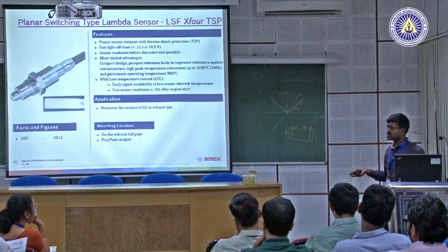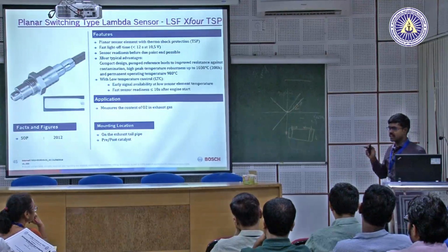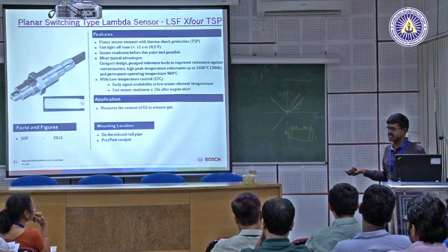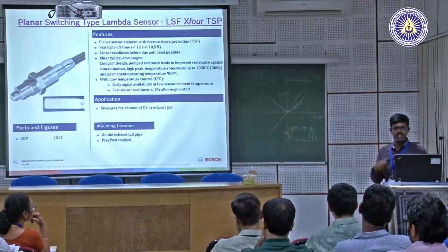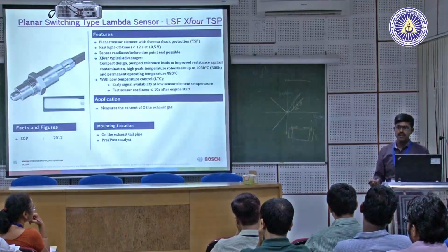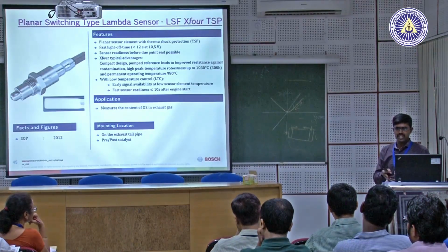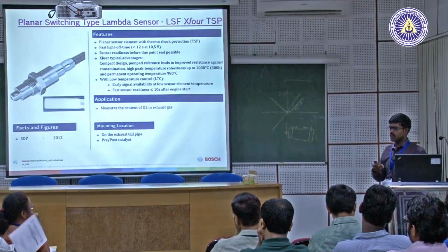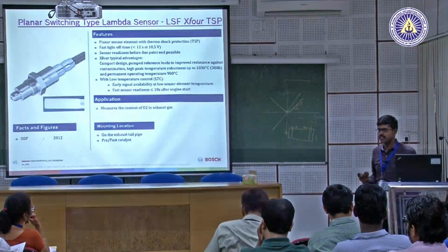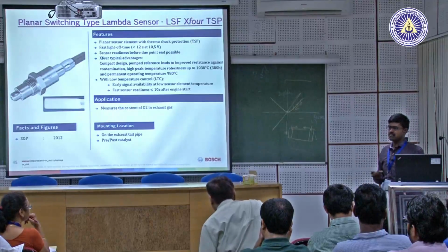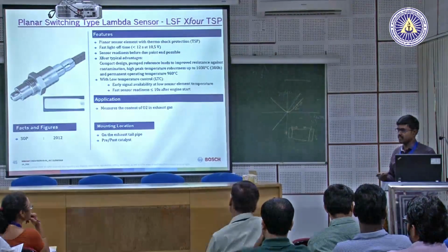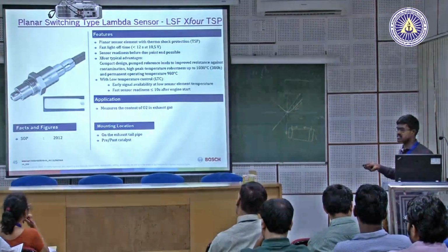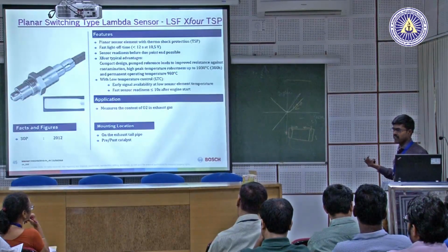Before and after combustion, if the oxygen amount remains the same at 20%, it means there is no combustion at all. For combustion you need oxygen, to create a flame, to have a mixture and to do the combustion. Proper combustion utilizes more oxygen, and that tells you that you have done a proper combustion. So with the amount of oxygen in the exhaust gas, you can come to know the combustion level.